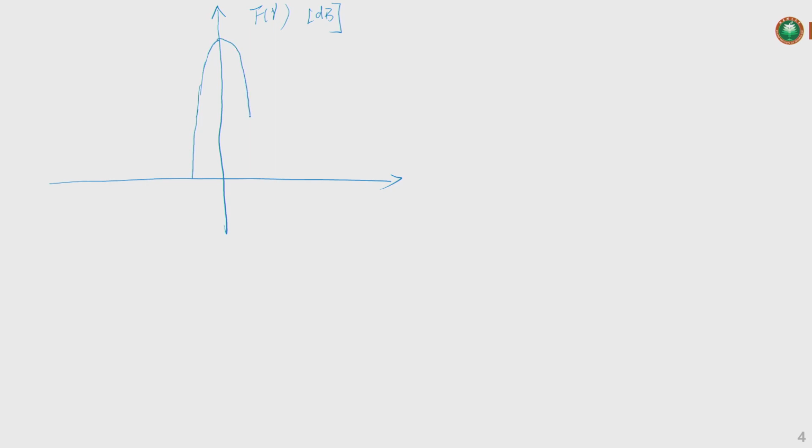The main beam, this, and the x-axis refers to gamma, which equals pi Lx over lambda times sin theta, right? So this is the maximum, and here is 0. So this one is 0 also, dB, and here is minus 30. For example, and the side lobes.